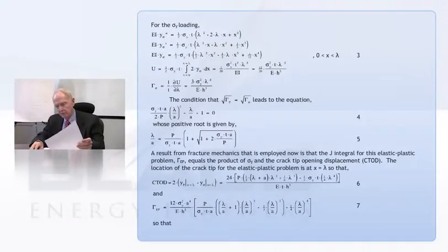You're looking at the region on the beam from the tip where the load is applied to the depth of the sawed crack, or actually it should be the real crack that's slightly extended beyond A. And then beyond that, the plastic region, lambda. So you apply the load P and do a plain vanilla beam theory solution, as though that was a built-in beam with load P. Then you turn around and for the loading with the yield point load, you solve that flat out as a beam problem.